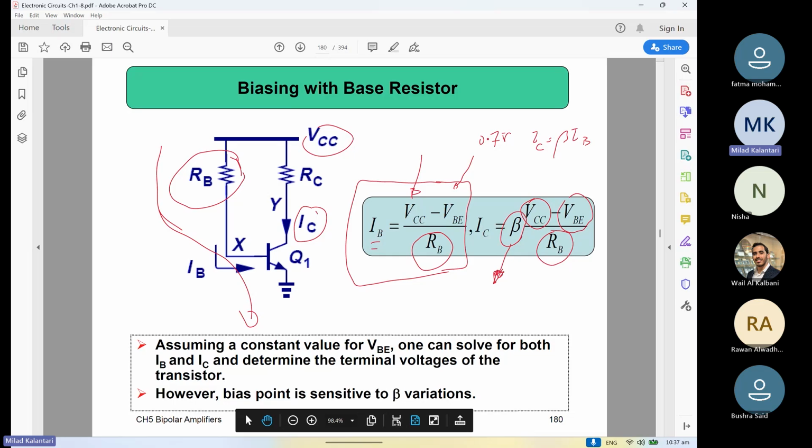But the VBE, in certain cases, is a little bit better defined. You can tell that the VBE on is something around 0.7, but it still varies between different device sizes or device types. If you use silicon, maybe it's close to 0.7, but if you change the device to something like germanium, it may be smaller, right? But one more important parameter that does not show up directly here is the temperature.